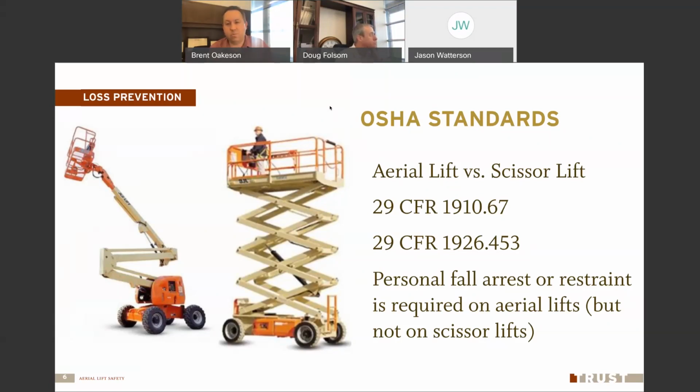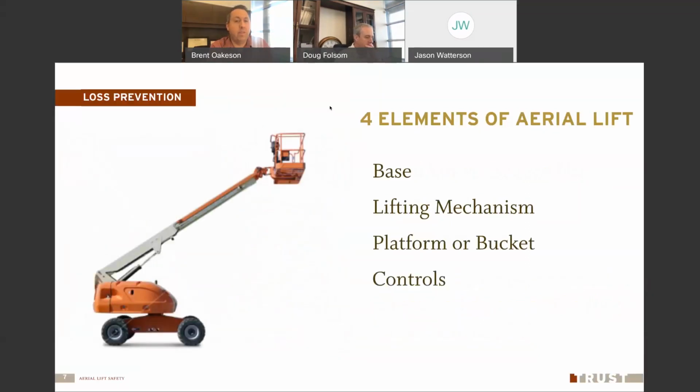However, I've seen on projects where general contractors or owners of a project will require that you tie off inside of those baskets anyway on a scissor lift. Whether it's required by OSHA or not, that could be a site requirement, and definitely something that we recommend at Trust. You might as well tie off. They have the connections for it in those. And it keeps you from falling out if you hit a ledge or you get bumped out somehow, it keeps you from falling out over those guardrails. So definitely a recommendation to be tied off in those, even if it's considered a scaffold.